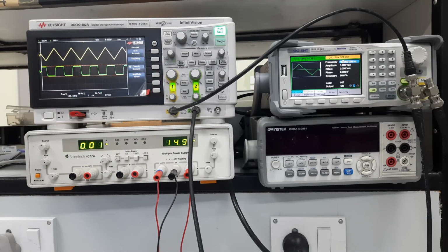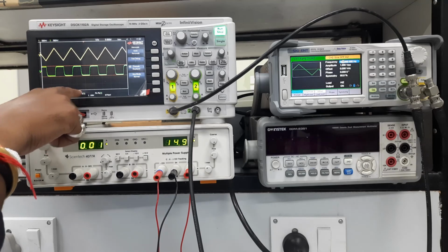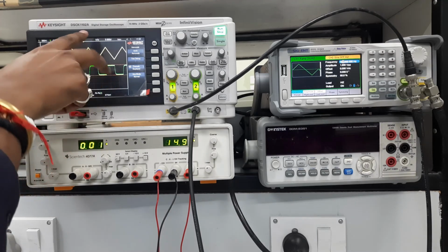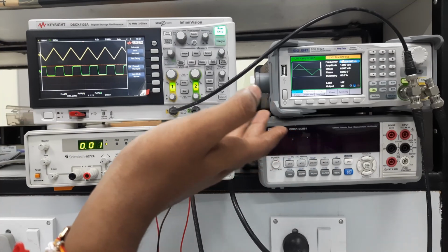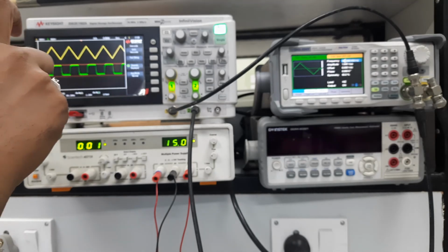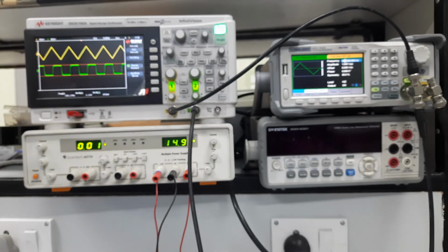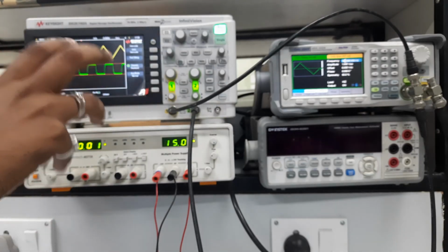Okay, so these are the things in this experiment, and what you have to do is, the data will give you the display of this DSO. Here you will find the frequency, amplitude, and peak to peak amplitudes of both the input and output signals, for the different wave shapes. In the case of adder and subtractor, you will get 3 to 4 different input amplitudes with the corresponding output signal.